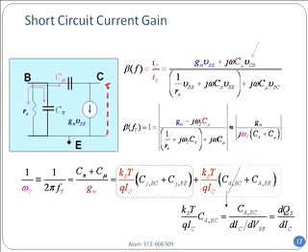But before I do that, let me convince you that the capacitance divided by the current can be written as the Q_B divided by I_C. Do you agree with this statement? Because you can see that q I_C divided by kT, couldn't I write it as dI_C over dV_BE? Remember, that is how I pulled out q over kT a few seconds ago. And if I flip dV_BE from the denominator to the numerator, then C multiplied by V, what is that? That's the charge. So this becomes the charge because I have flipped this voltage up in here, and dI_C comes in here.